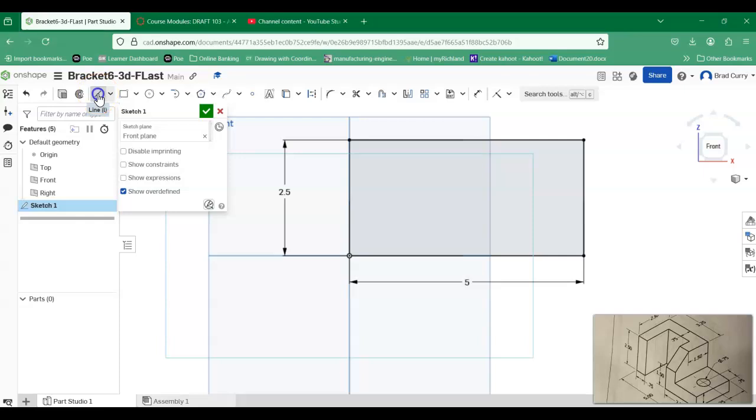In this case, I'm going to create a line. I'm going to left click. This is going to be a horizontal line and then a vertical line up to that point. We'll hit escape. So now let's use the trim tool. So right here's the trim tool. I'm going to trim this point out and trim that out. So we're getting this big goofy L shape here.